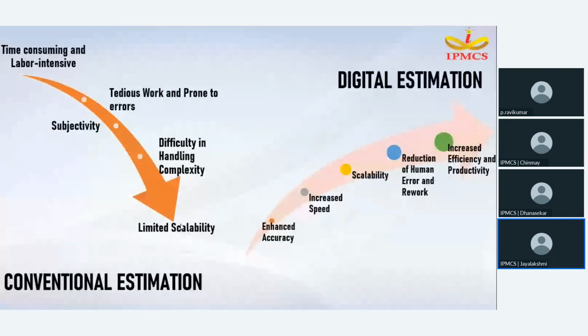But when we are using Excel plus AutoCAD, which can be termed a conventional estimation method, the estimators have to analyze and study each drawing, physically identify each element, make a list of elements, and then quantify them. Before quantification, we have to load each element into predefined cells in the Excel sheet, and formulas can be created.